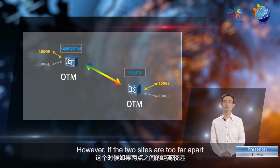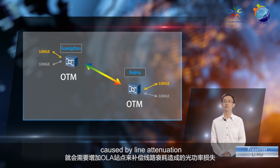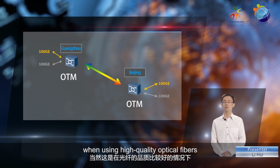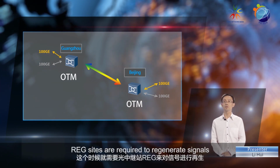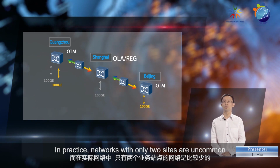However, if the two sites are too far apart, then OLA sites are required to handle the optical power losses caused by line attenuation. Generally, an OLA site is required every 80 kilometers when using high-quality optical fibers. If the OSNR is severely degraded during transmission, REG sites are required to regenerate signals. In practice, networks with only two sites are uncommon.